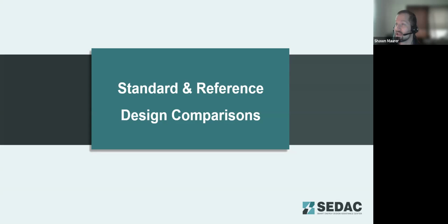I did have a question come in for the last section regarding exceptional calculations. The question was: do the exceptional calculations include settings that are programmed on top of the compliance software but run within that simulation, or only analysis done outside compliance software? The exceptional calculations would apply to any calculation that you're doing outside of your compliance software. If you're running programming inside the compliance software, it does have to comply with that ASHRAE 140 document, but that is within the compliance software, and so it is not considered an exceptional calculation because it's being done by the software. What they're trying to limit with the exceptional calculations limitation is a lot of calculation outside of a standardized compliance software system.